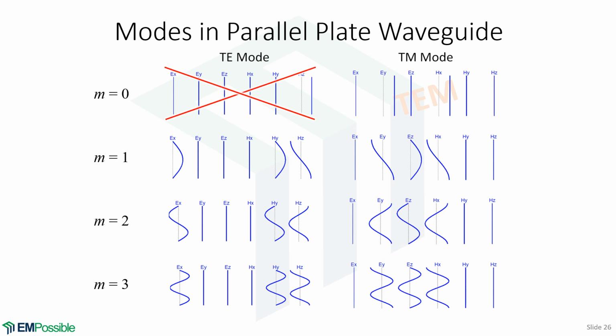I've plotted the first three order modes. We have equations for the TE0 mode. We know that it's not a physical mode. I went ahead and plotted them and X'd them out to remind us those don't actually exist. Our TM0 mode, notice everything is straight and uniform. That is clearly the TEM. And here's plots of the other modes. And it's a little bit more obvious here how we are looking at two half bright spots. So there's our modes.